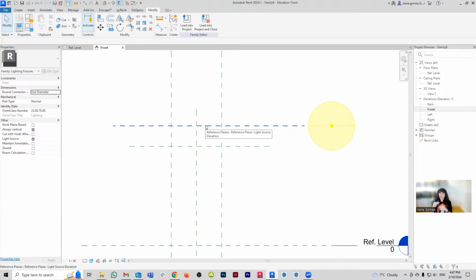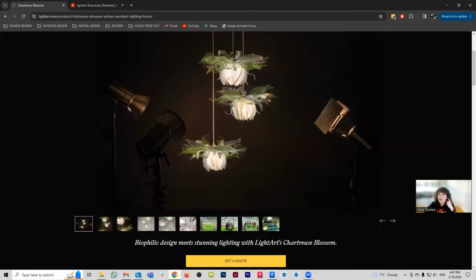Basically these petals are going to be a two-part. Part one is going to be simply an extrusion that is just going to have that curvature. And then I'm going to create a void from the top down to cut them into that leaf shape. Usually when I'm building with Revit geometry, if I can get away with making something as an extrusion, I will do that because extrusions are the easiest thing. You can think about extrusions as a cookie cutter. It's just a shape and then you cut it.